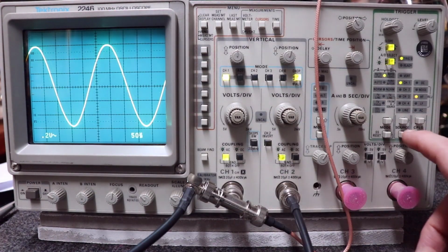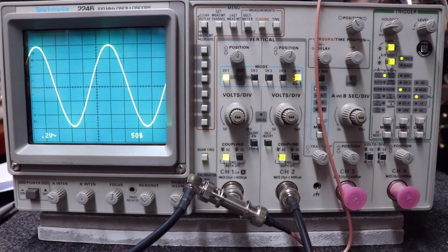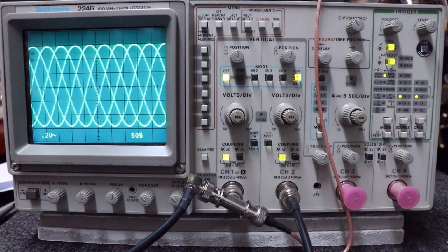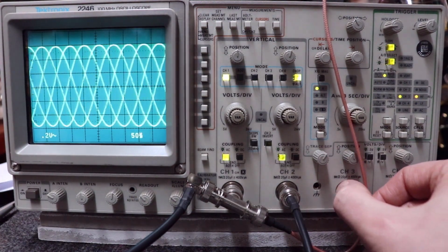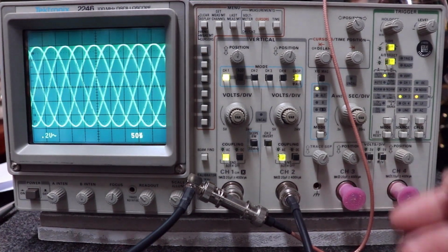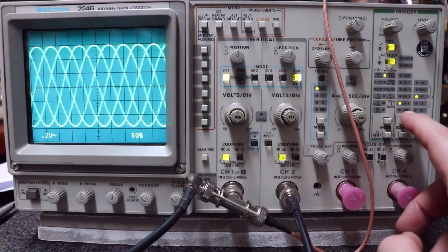along this way. If I go to channel 2, the other channel, remember I'm feeding the same signal into it, so it happens to trigger the same. But if I'm triggering on channel 3, guess what? There's no input into channel 3, so I have no idea what it's triggering on right now, and you can never lock in because of that. The same with channel 4 here.